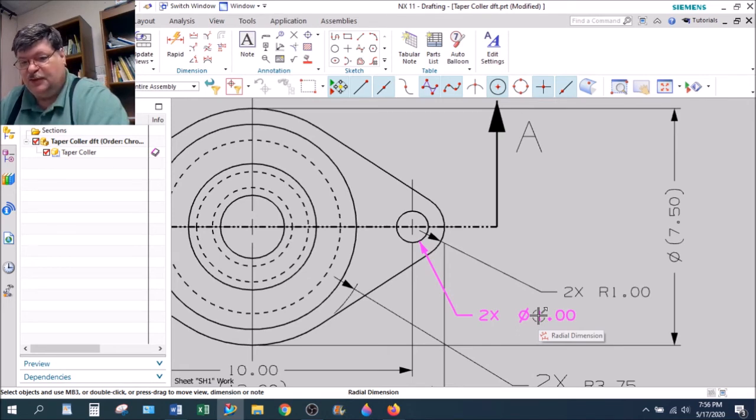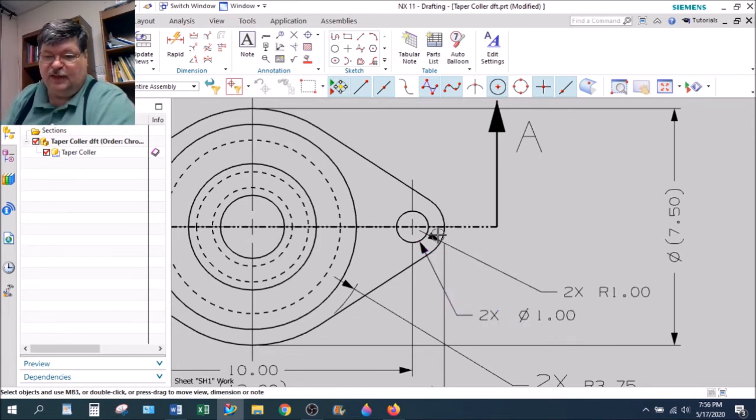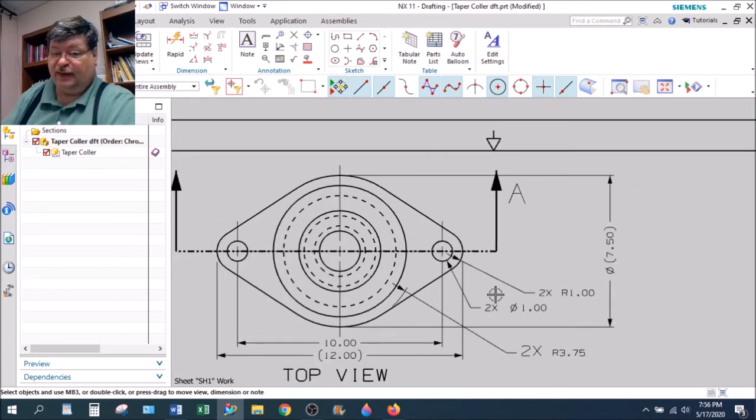Also in some CAD programs like AutoCAD, and in this program also, the dimension is actually associated with the feature. So if I were to go in and change the feature and make it larger and then come back to the draft view, it would automatically show a larger number. If you break the leader line, thus breaking the dimension, it would disassociate itself from the feature, and if you change the feature size, a lot of times the text won't update. You don't want that happening.